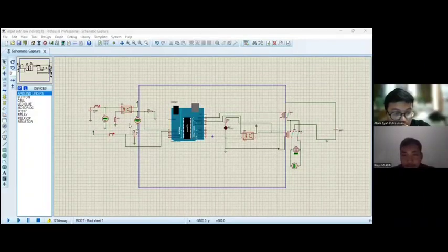Suppose the simulation starts but the voltage button is off. The button that determines right or left motor will not work, but if you press the lower button it will work. When the top push button is pressed, A0 is 1 and the DC motor will be high. But when released, it will be 0 and the DC motor will be low.